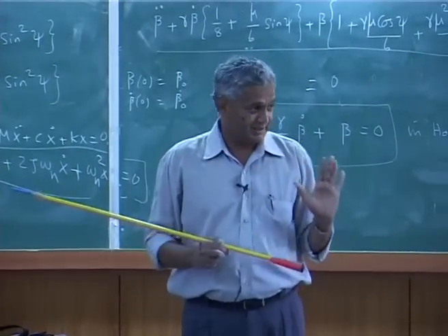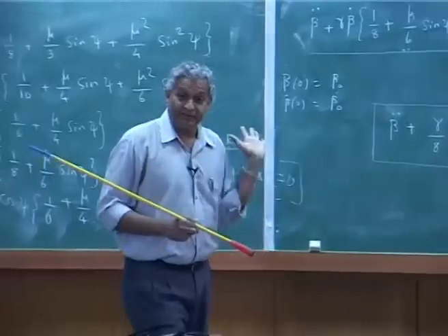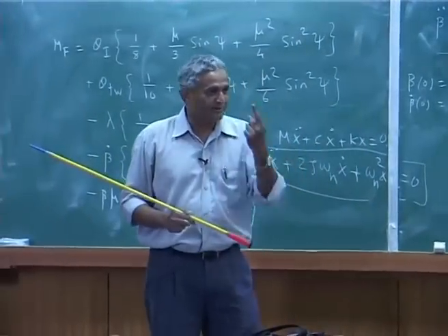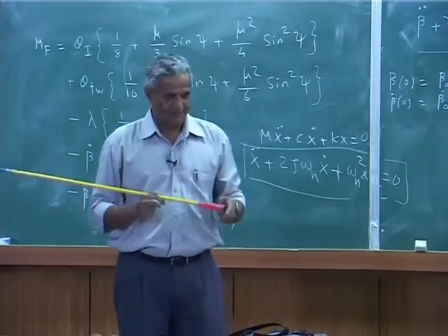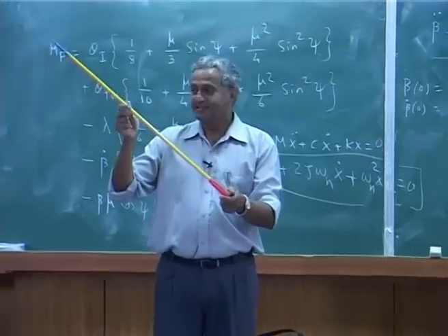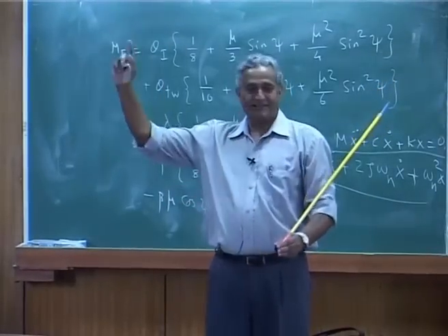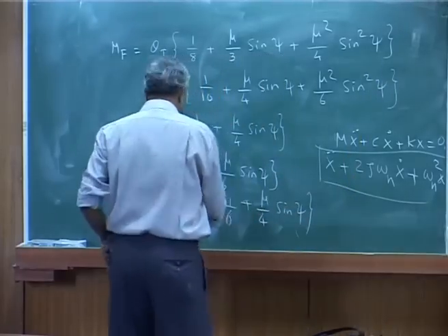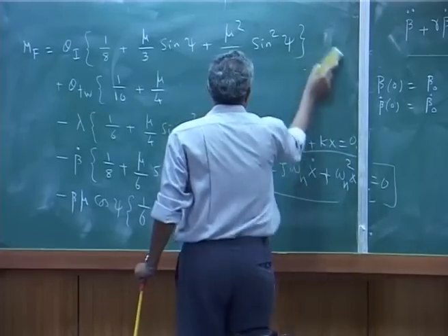Only in this case, please understand. That is why we call it 1 per rev. 1 per rev. 1 oscillation per revolution. Okay, that means if you tap it up, it will go down and then up, down. Then when it comes to 1 oscillation, the blade would have gone through 1 revolution.